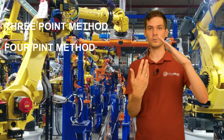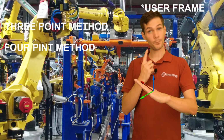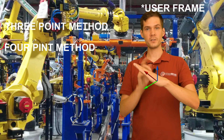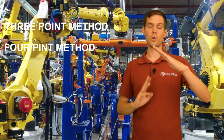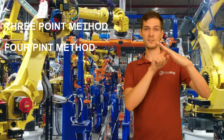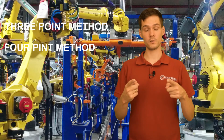So what you're going to do is teach the frame here, and then with that 1 point left, the 4-point method, you're going to shift it from here to here. So you don't actually need to go to those points. You're only going to tell the robot, hey, the plane looks like this, but it's not located here, it's located here. And that's why you use the 4-point method. Cool? Pretty cool.